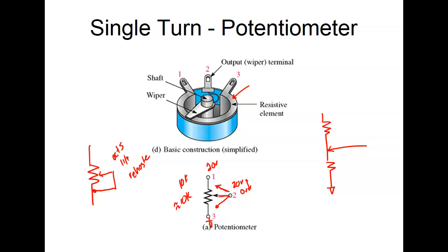So when they figured this out, it basically did away with the rheostat. Every time we buy a pot, I can make it serve two functions. I can make it serve as the rheostat, or I can make it serve as a variable voltage divider. And what we're doing is constantly changing the ratio of these two resistors depending on where we set it.